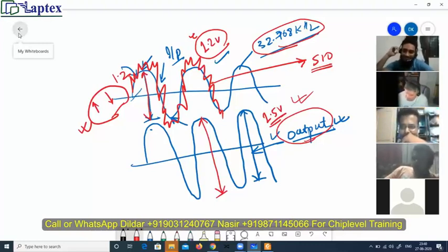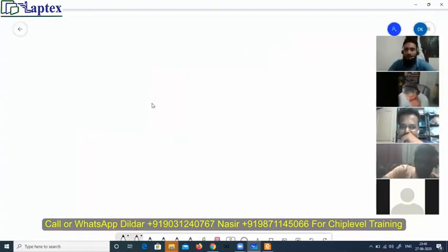It is not a feature of a soldering iron. The multimeter gives you that one second: when you touch it at that second, what is the voltage? But if you put a DSO there, it's like a movie. You see how the signal was before, if something changed or not, what happened. Your multimeter is not measuring that at all.